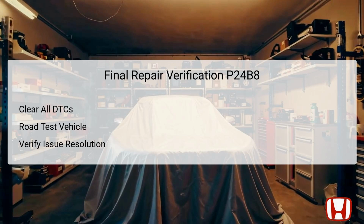resolved. Start by clearing all diagnostic trouble codes, DTCs, using the HDS, effectively resetting the vehicle's onboard diagnostics. Following this, perform a road test under normal driving conditions to ensure the vehicle operates without triggering the previously encountered DTC P24B8. Monitor the system for any signs of abnormal operations or warning lights, as this step confirms the effectiveness of the repairs made. A successful road test and the absence of the code would verify that the repairs conducted were indeed effective and that the vehicle is back to optimal performance.